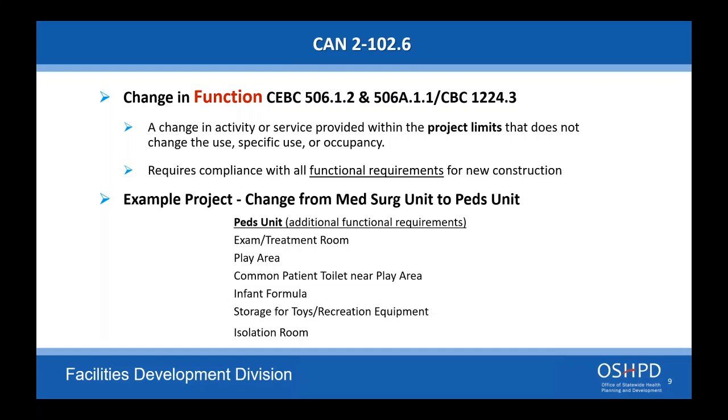Tile's not such a big deal, but with carpet or wallpaper, things like that, there may be flame spread or smoke type ratings that they may ask about. So I want to clarify that for cosmetic work, a permit may not be required, but you do want to contact the compliance officer to not only let him know what you're doing so that he knows there is something happening in the facility, but also so they can check that stuff to make sure that you're putting in a product that is going to be compliant.